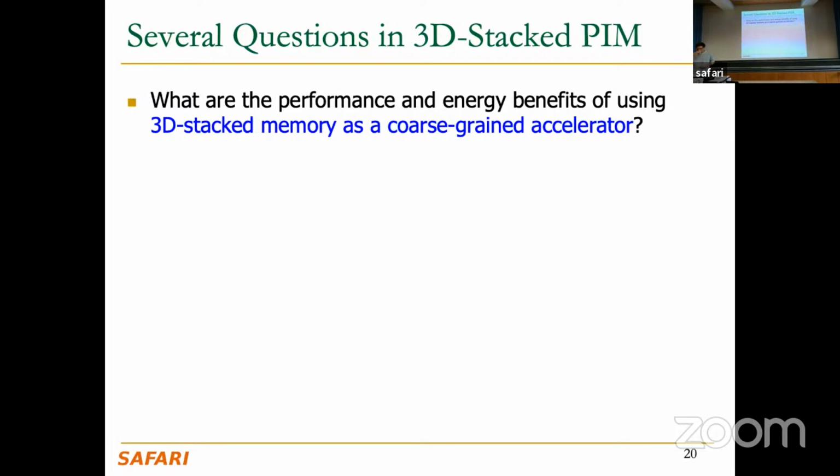It's something I mentioned yesterday. When you try to create logic inside a DRAM chip, same as UPMEM did, it's going to be very challenging to have a powerful core. The reason is that the technology itself is for different purposes. DRAM technology is not created to have fast switching transistors, for example, and that limits the design of the processing elements or accelerators in that type of technology.